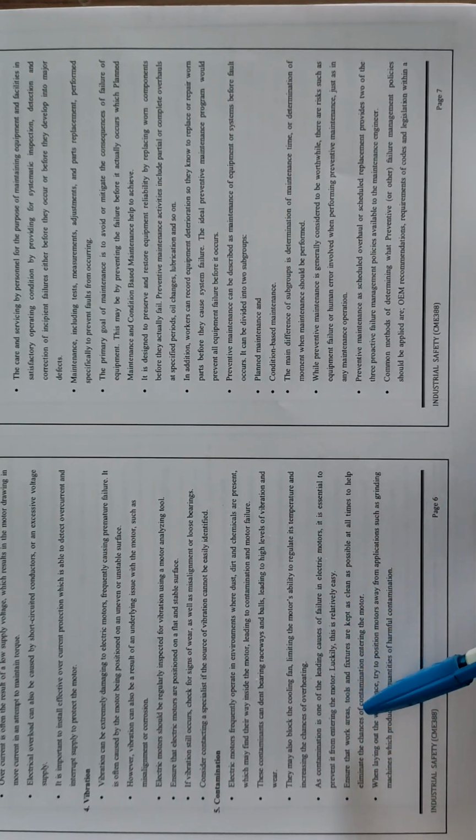Ensure that work areas, tools, and fixtures are kept as clean as possible at all times to help eliminate the chances of contamination entering the motor. When laying out the workplace, try to position motors away from applications such as grinding machines, which produce large quantities of harmful contamination.